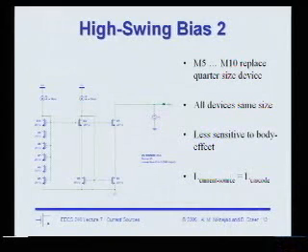Okay, so remember the point is to design a circuit that has high output impedance, so it's like a cascode current mirror, and also to try to achieve the largest swing possible. And we realize that in a straightforward cascode, you're kind of wasting a threshold voltage. So we want to come up with a circuit that gives us just the right voltage at the gate of the cascode transistor to provide us the maximum possible swing.